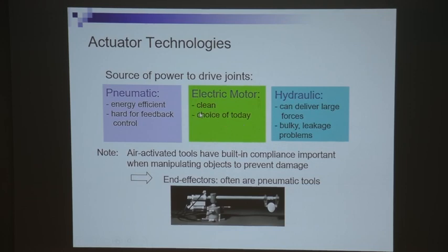The electrical motor is clean, and on the other end you have the pneumatic and hydraulics. The pneumatic one is more energy efficient, but it's harder for feedback control. The hydraulic one can deliver a large force, but it tends to be bulky, and there may be a leakage problem and so on. But all these are general. When people ask you why an electrical motor is being used, it's typically because of this general perception of the different motors. Depending on your application, you may choose to use a hydraulic motor.